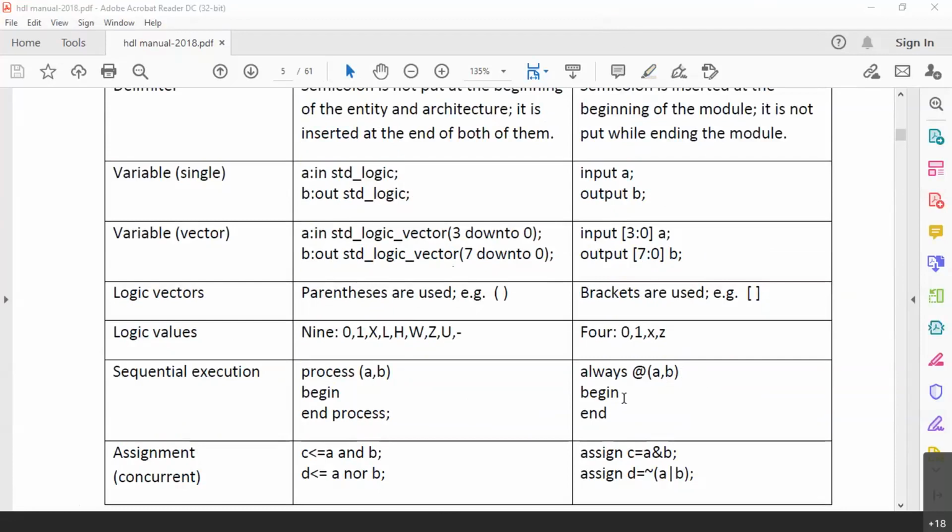Okay, here the semicolon will come as a delimiter. After always, we are starting one block called always. Inside this begin and end, we will have other execution statements, many of which are going to be assignment statements or executing statements. So a semicolon will come only when there is a delimiter separating one statement from another. Here this is not an always statement, it is an always block.